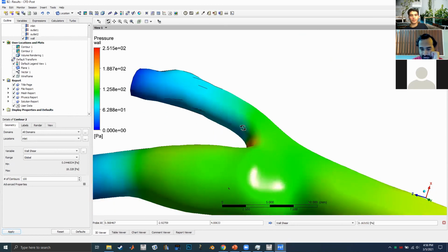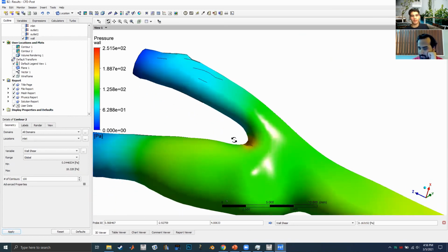For the actual CAD model, is it assumed to be a specific material? In this case, the wall, or the model for the physical geometry. The CAD model is literally just points in space connected by triangles. You apply whatever material you want to it. Ansys Discovery Live has a built-in material library, but you can also say, this piece in my component is actually made out of steel, this one's made out of rubber, this one's made out of wood, whatever. And if you're dealing with the fluid component, Ansys has a list of air, water, oil, or you can make your own fluid that has certain properties.